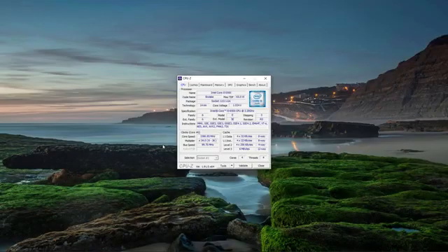I just want to show you some information about my own PC, which I'm getting from a little utility called CPU-Z. You can download this for free. Notice the bus speed, which is just under 100 MHz. This is actually the base clock frequency coming from the crystal oscillator. I can also see here that it says multiplier, which is around 34-36.